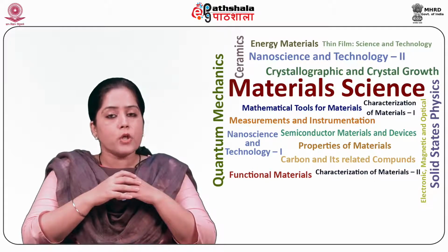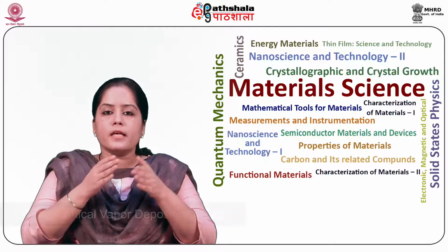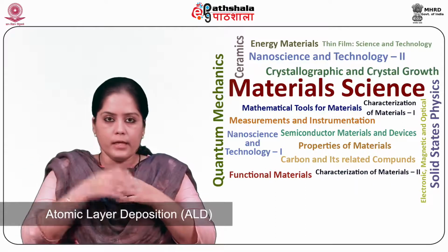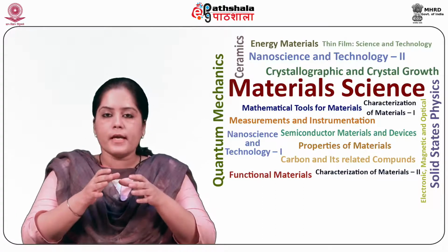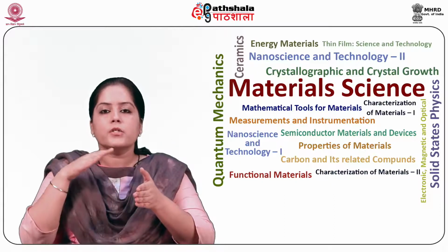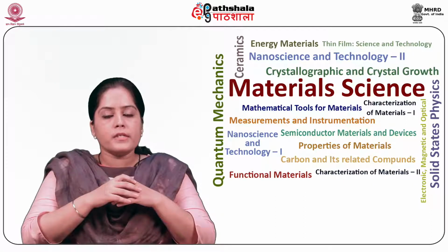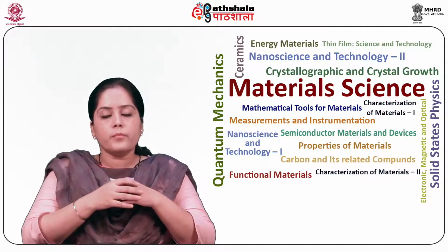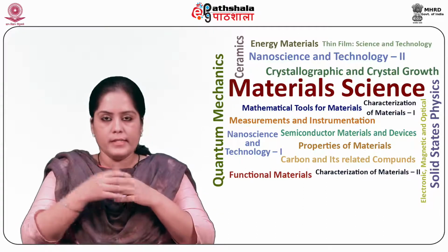This field is dominated by mainly two groups. The first group comprises chemical vapor deposition, CVD, and atomic layer deposition, ALD. Both these techniques comprise a process in which the gas phase is used to transport volatile molecules to the surface serving as substrate. The second group has a technique known as chemical solution processing or Sol-Gel processing, which uses the liquid phase as the mass transfer media.